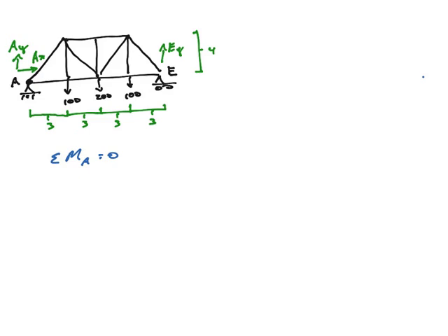What do we have? Well, we've got the 100 force pulling down. That's going to cause a rotation. Its distance away is 3 meters from the point of rotation. That force tries to make my truss rotate clockwise, and clockwise rotations are always negative in physics, so that moment is negative. Then I have a 200 Newton force at a distance of 6 meters away from A.